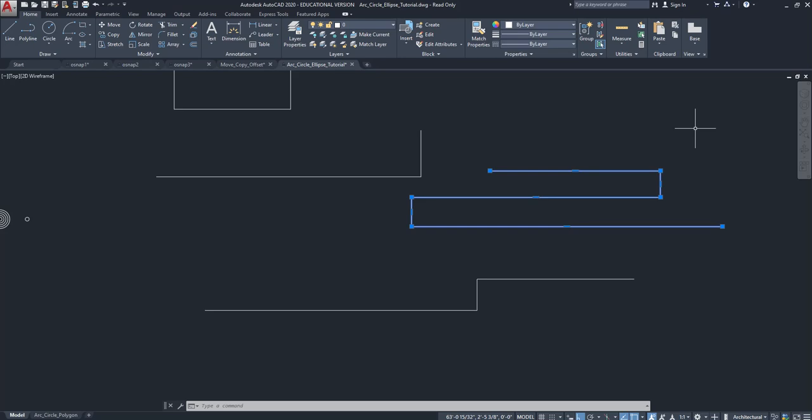Again, once you start getting into AutoCAD and you use it more, you'll figure out when and where you feel like it's appropriate to do different things. Polygons are really nice because they are cohesive. So if you draw floor plan lines with it, you move it, they all move together, right? So that's nice. When we get into hatching things, right, adding those shades, the poché, solid, earth hatches, cross hatches, whatever, polygons are really nice because they're a closed region, which will allow hatch to form, okay? And we'll talk about that when we get there. But a polyline is really just one line that is all glued together, okay?